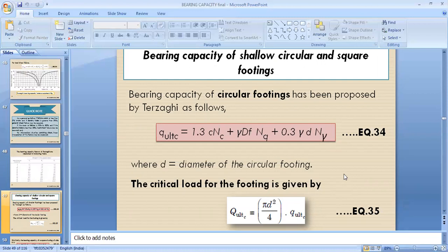We'll see in the next lecture, given Terzaghi's equation C Nc plus gamma D Nq plus 0.5 gamma B N gamma, which was originally crafted for strip footings, shallow foundations, how this theory can be advanced to other types of footings like circular footings, rectangular footings, or different kinds of footings. This we'll study in my next lecture.